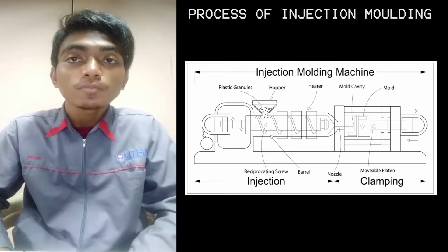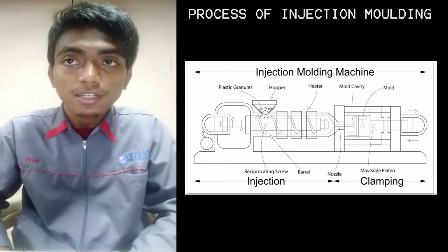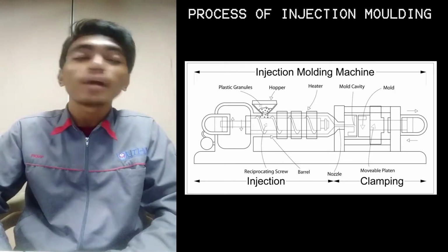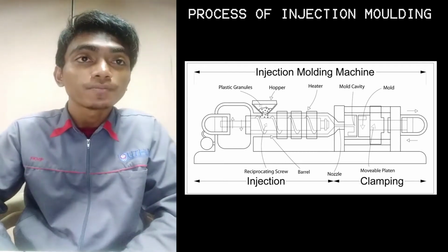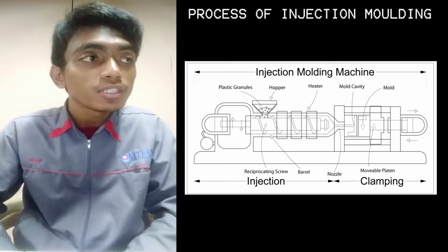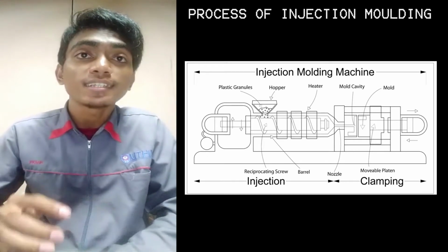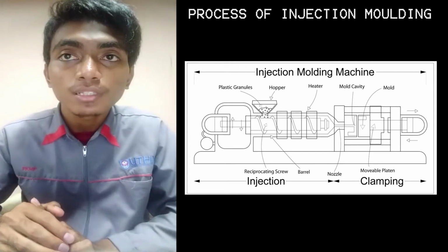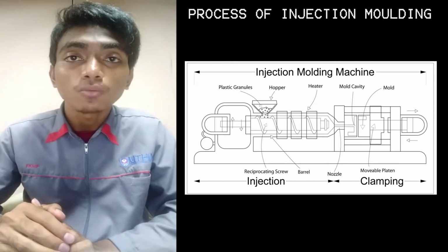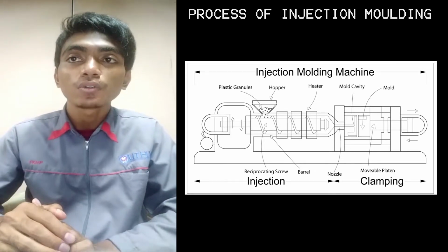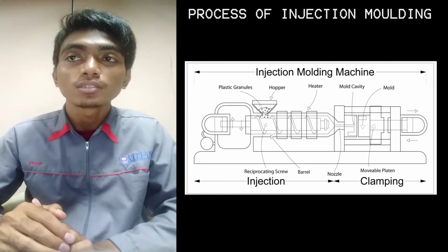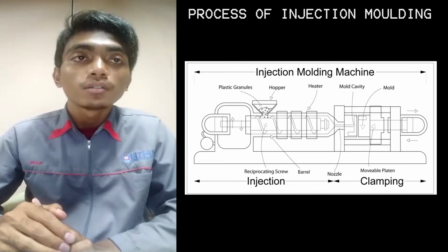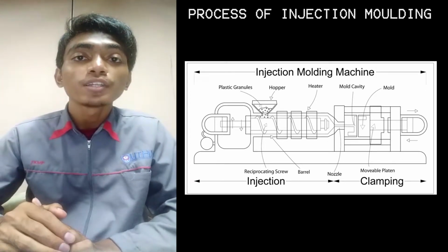The molten plastic is then injected very quickly into the mold through the nozzle at the end of the barrel by the build-up of pressure and forward action of the screw. This increasing pressure allows the material to be packed and forcibly held in the mold. Once the material has solidified inside the mold, the screw can retract and fill with more material for the next shot.